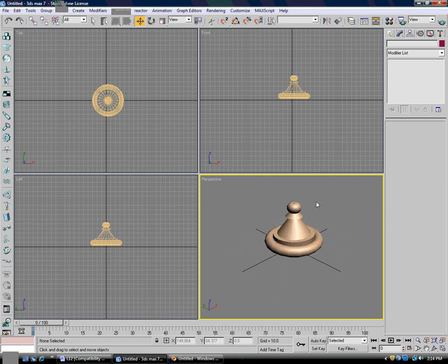So those are the steps you have to perform creating this type of complex structure, which has symmetry about one particular axis. You can create half of a cross section and do the lathe operation to complete the structure.